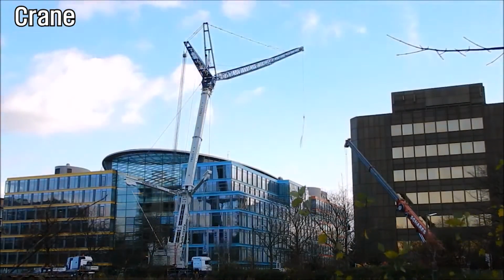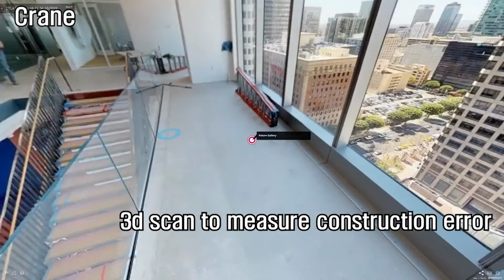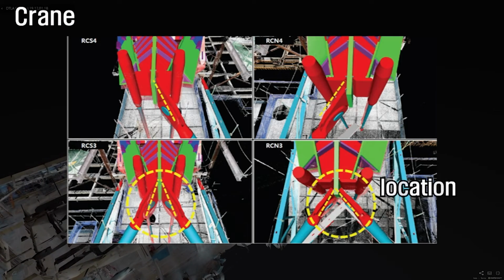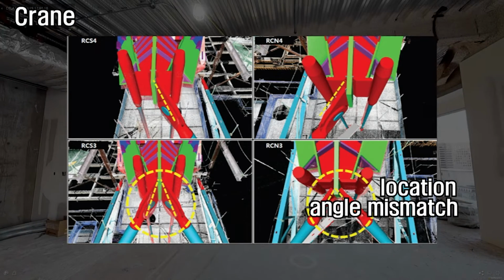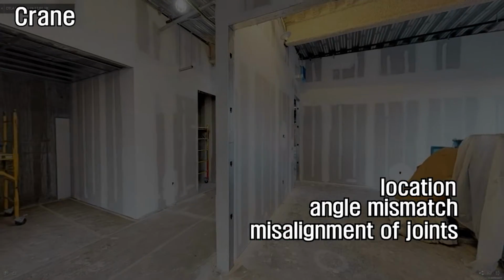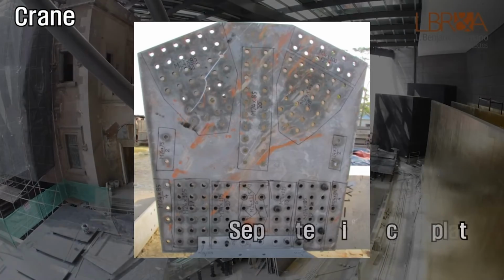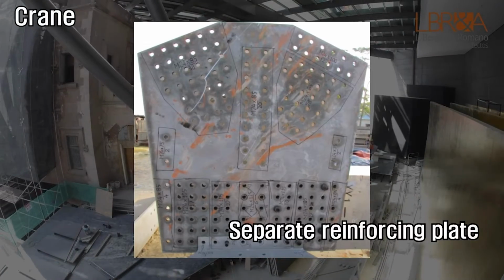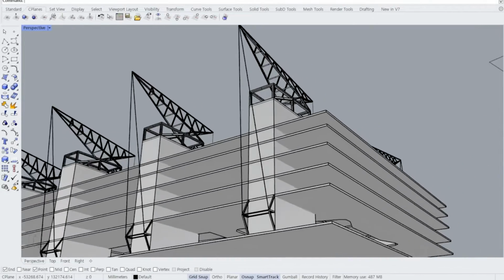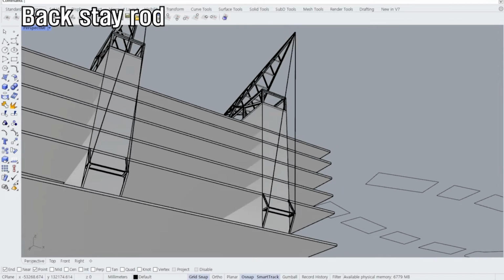During the installation, they ran a 3D scan to measure the construction error. It was confirmed that there were some errors of location, angle mismatch, and misalignments of the joints. To correct this, some sections were reinstalled, and a separate reinforcing plate was installed for the joint to secure the stability. Finally, a backstay rod was installed to connect the crane and the ground layer of the core.